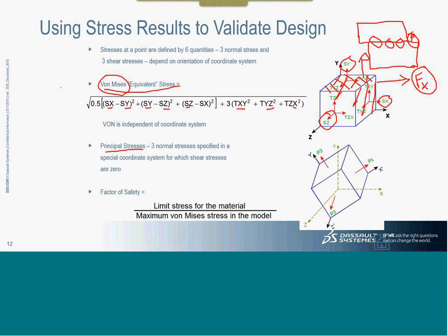And for practical purposes, if it is a ductile material, then users accept the stress representing the normal and shear stress as a stress which can be compared with the yield strength of the material to decide if the part is going to fail or not fail. These are the basic ingredients of von Mises stress, and the reason why it is used exhaustively and has its own place is that for most of the geometries we end up using this particular stress.